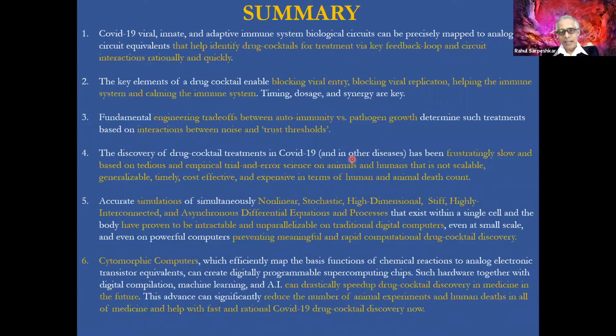Yeah, memristors are basically a technology that allows you to remember things. So they have an advantage in that the analog memory, which in the version that I showed you is being done digitally, can be done more compactly. But one of the disadvantages of memristors is they have a finite number of cycles. So if you, for example, learn 100,000 times, you might destroy them because of the physics of the device. Whereas a digital computer can be programmed infinite numbers of times. So if you're storing the bits and the parameters digitally, there are some advantages to it.